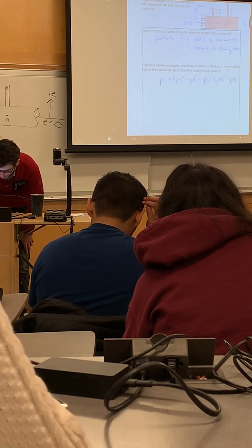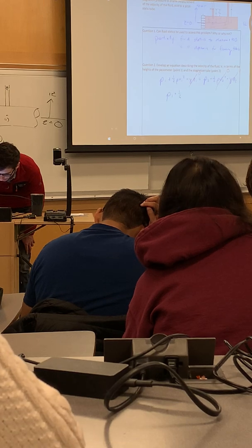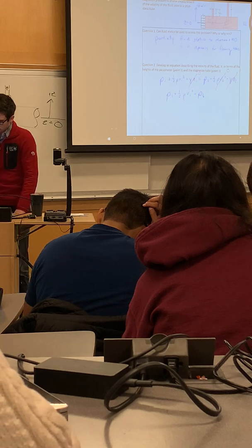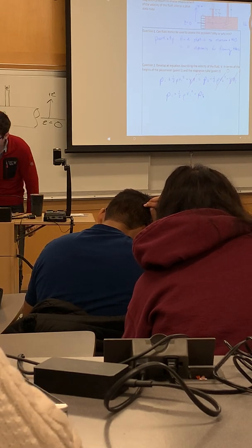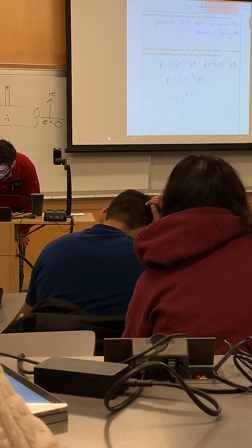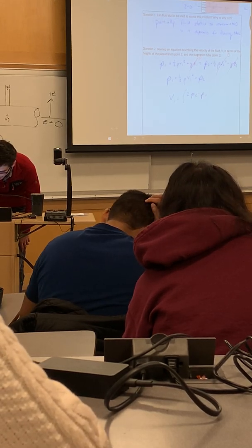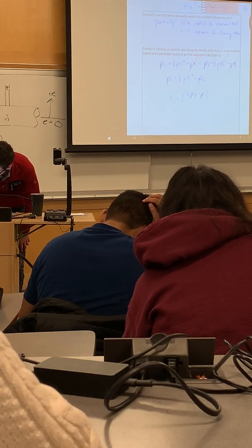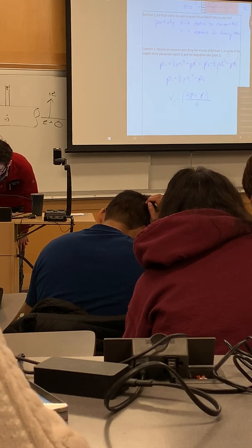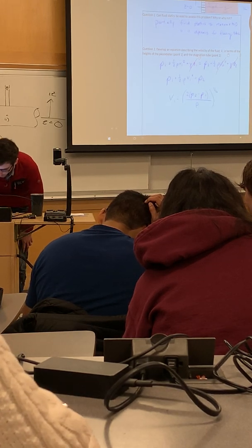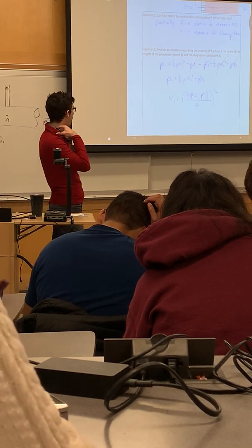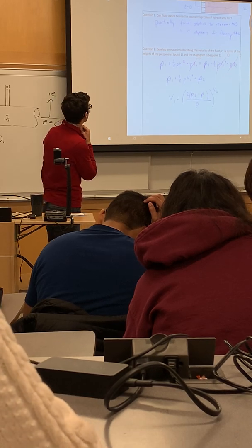So from this, we get P1 plus 1/2 rho V1 squared is equal to P2, right? And we can solve this for V1 is equal to 2 times P2 minus P1, divided by the density, all to the 1/2 power. Okay, so that's our expression for the velocity